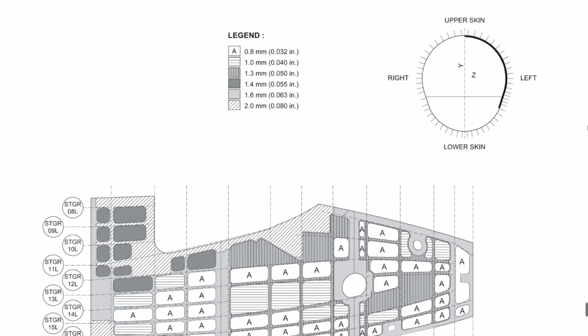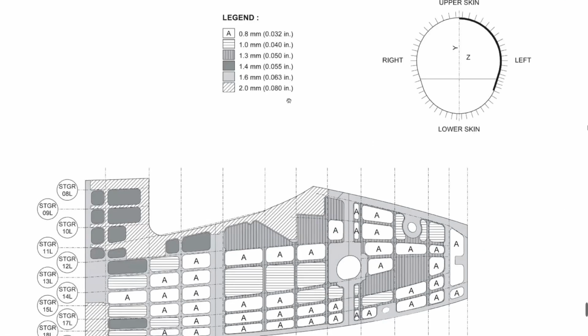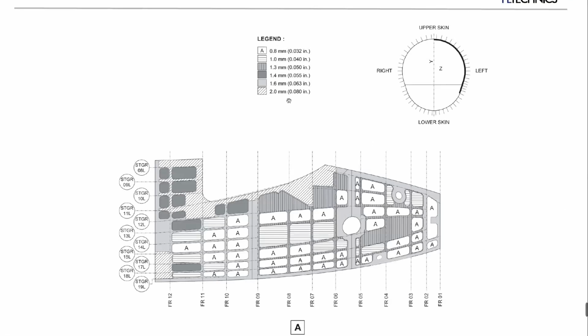So he started to blend out, and then suddenly, when the NDT guy measured the remaining thickness, it was out of the limit. Okay, that's why I told you, be careful when you're performing blend out. On some locations, the skin thickness is really low.